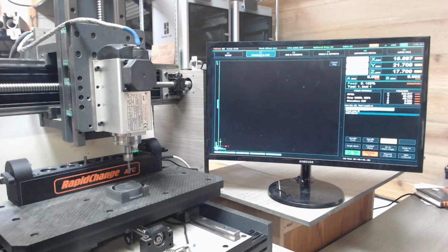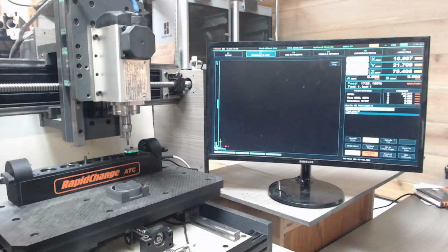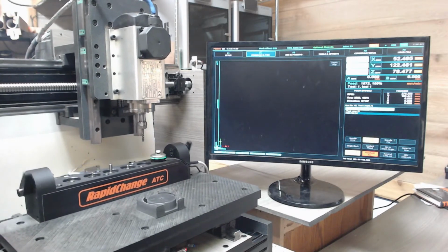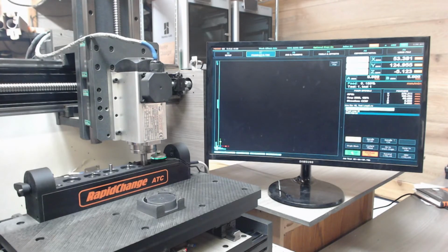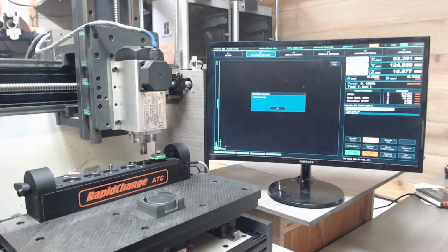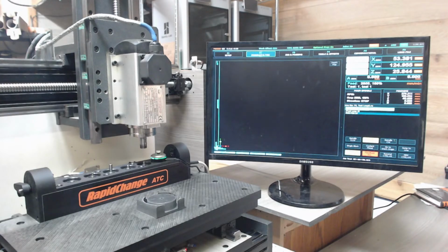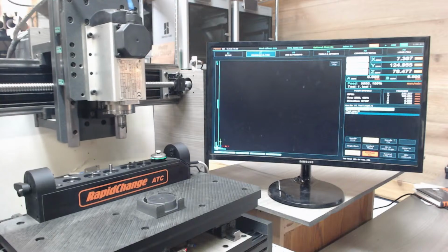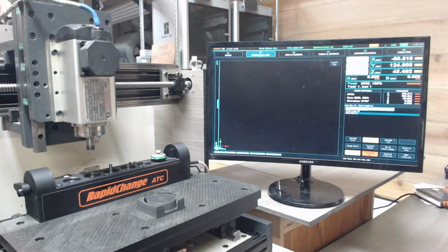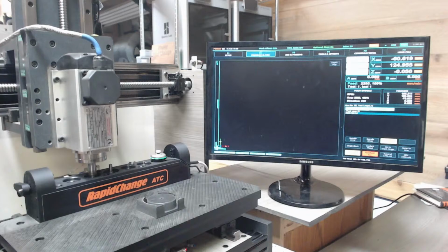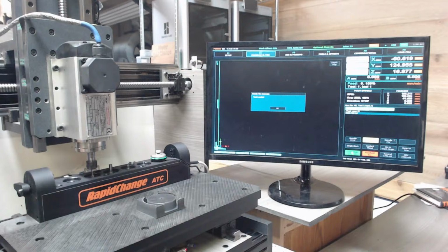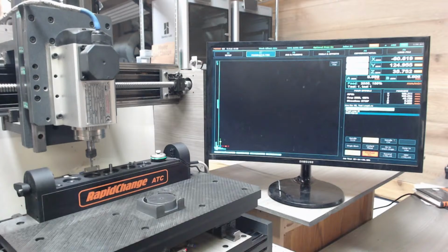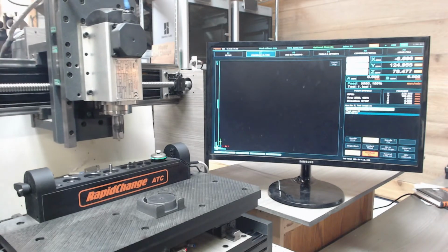So getting your spindle to spin both directions really is just a matter of wiring a relay to the pin on the VFD that controls reverse, and then to get it to spin slow enough to make the tool change without destroying the sockets in the magazine, there's generally a minimum setting on the VFD and generally in the control software, depending on which one you're using.